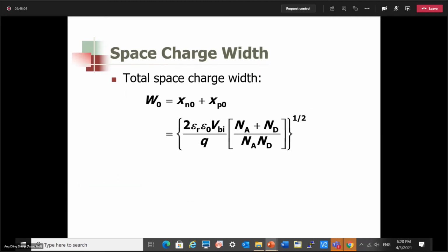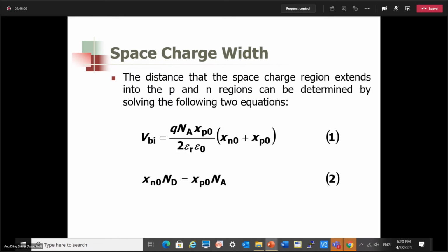So if you go back to the space charge balance equation here, and add in the electron and hole terms, they are much smaller than this and this term. So if we neglect them, we do not violate the conservation of charge very significantly. But you are right that this is an approximated form. Okay, thank you.